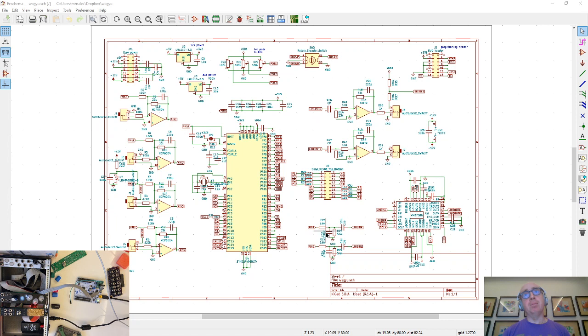So there's a little filter cap and a thing to drain away any offset voltage, and then it goes into the codec, which is just the codec that I believe was in the original iPod, and JLC stock it. So it's a horrible little thing, but it works. And then for output, I just AC coupled output from the codec, so I don't have any DC coupled outputs on this device.